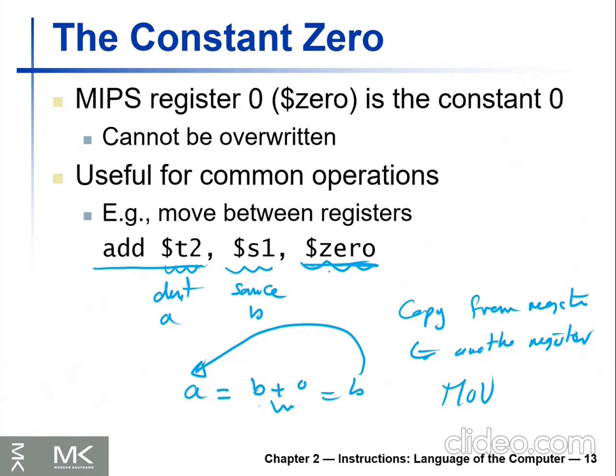So instead of defining a 0 immediate constant, you can use this register. This register has 0 all the time. By this, we don't create another circuit to do the move. We just use the same circuit that does the addition, which is really great. You save area, and this will of course simplify the design of your processor.